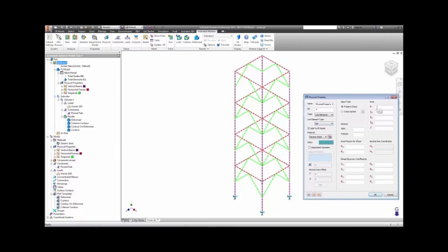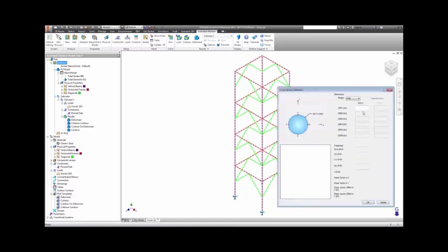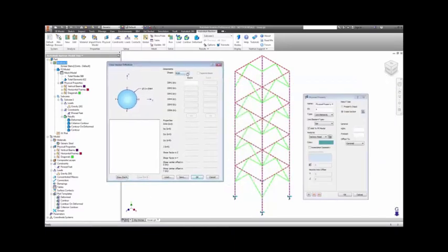Line elements require more properties to describe than solid elements and include things like cross-section area, moments of inertia, shear factors, and other normal beam section properties. Alternately, Autodesk Nastran IN-CAD has the ability to define a beam cross-section by its dimensions. There are a number of beam cross-sections included in a library available within Autodesk Nastran IN-CAD, such as channels, I-beams, T-beams, and box beams. To use this section, you simply enter the dimensions of your section beams as defined in the dialog box.